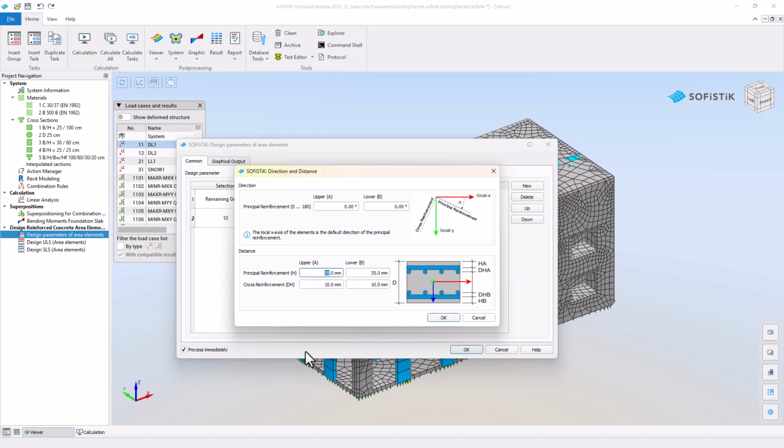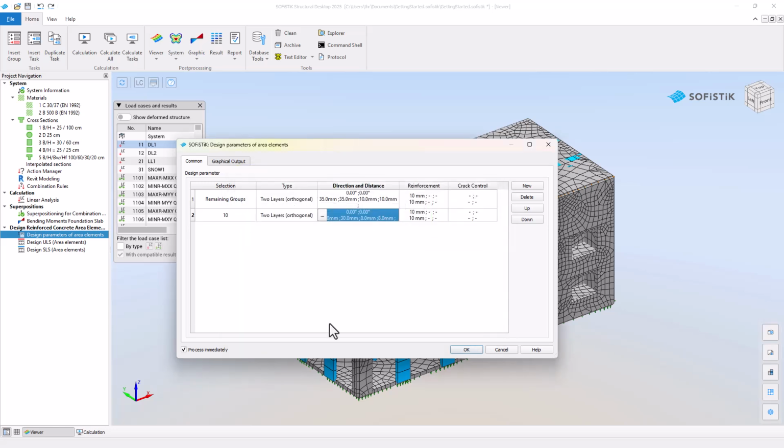We define the concrete cover at axis distances. With a nominal cover of 25 mm and a 10 mm diameter in the first layer, we set it to 30 mm to the first bar axis. Between first and second layer, we use half diameters. So for an assumption of diameter 10 and diameter 6, we set it to 8 mm.